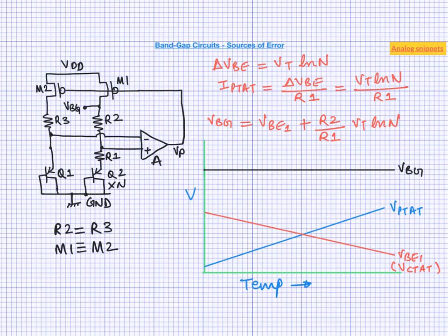Now this may seem strange, but this is actually true. PMOS acts here as a current source. So what matters here is the matching of the current. So what is important is the matching of threshold voltage here, not the absolute value of threshold voltage.